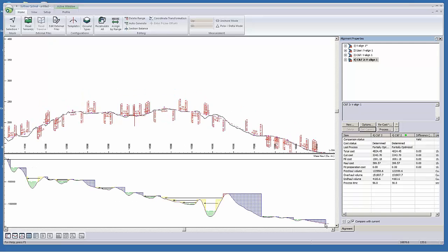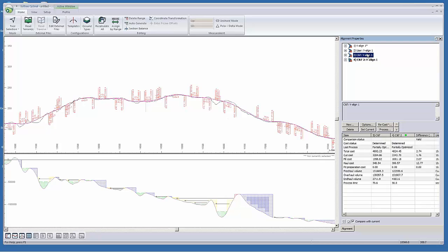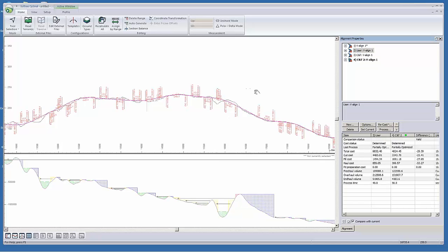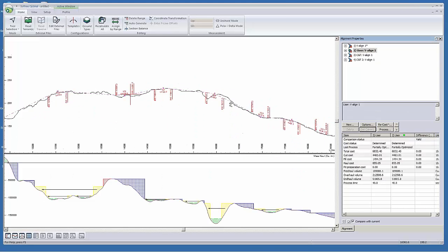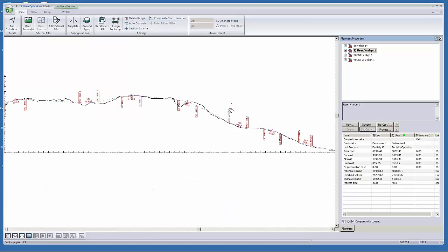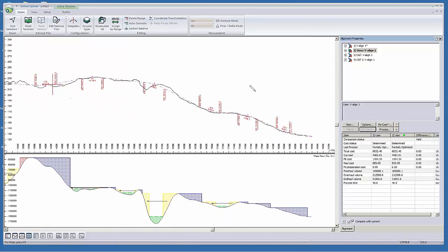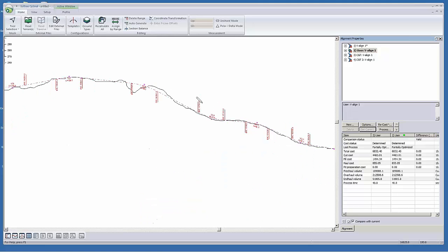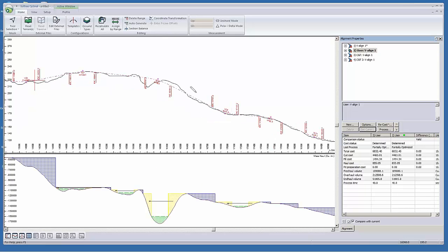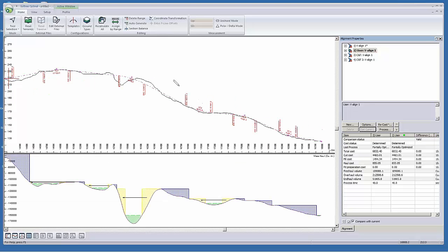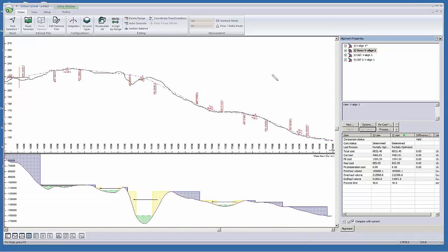I guess that's because we've got a lot of, that doesn't look right. Let's pick one that I ran right to optimality. It still looks a bit, not sure why our mass haul is so badly out of balance. It shouldn't be. I've obviously done something I shouldn't have done. It could also be the very coarse section spacing.